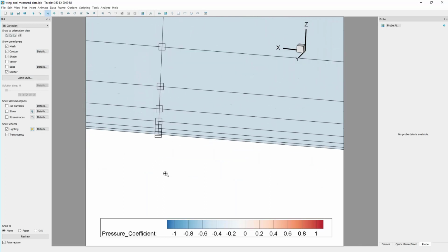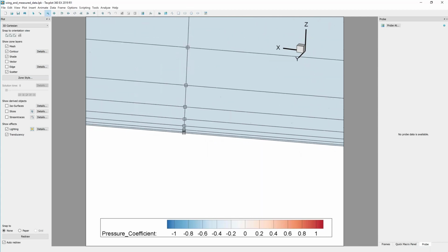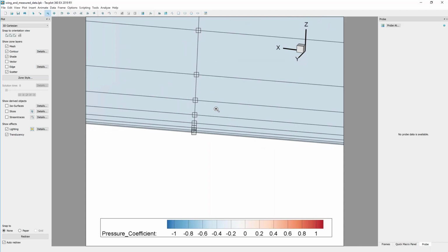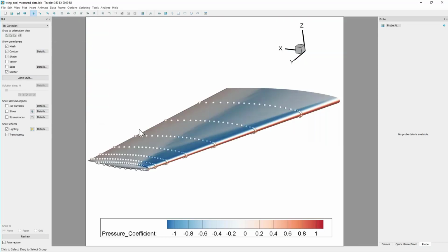So this is nice. This will capture all of the information in the boundary layer just perfectly with the cell density that you have. So a very nice technique for capturing that grid density and avoiding over specifying where your grid is thin. So that's extract a slice from a slice. Okay, so that's 3 techniques really quickly we showed you in about 10 or 15 minutes. So now let's start fresh again, and we'll dive into the Python portion of this.